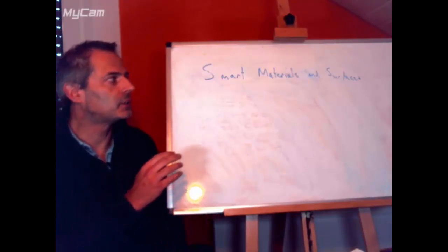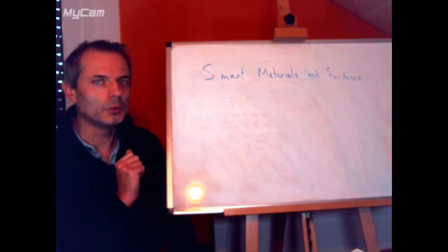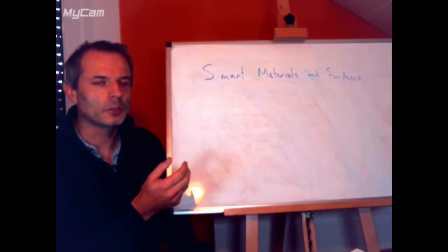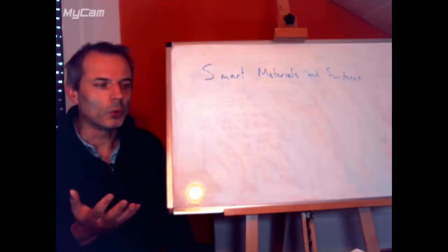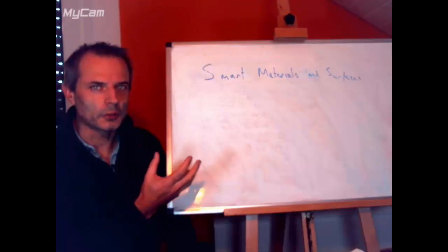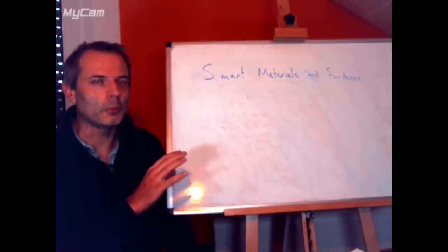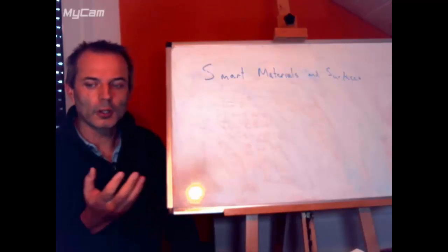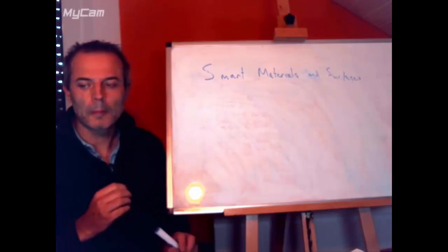It's one of a family of techniques where we measure the mass of things on a surface using an acoustic wave. So first of all, let's look at what's going on. The quartz crystal is what you would have in your computer or in your watch, and it's vibrating, it's oscillating under an electrical circuit, but the quartz crystal is determining the frequency. So it has a very sharp frequency resonance, and the clock in your computer or in your watch is using that to keep time.